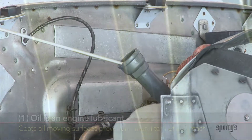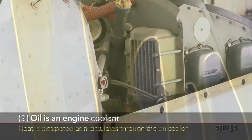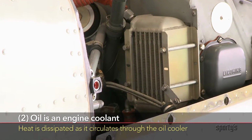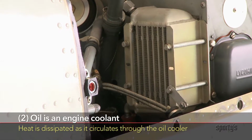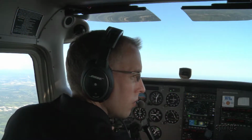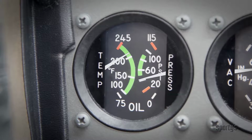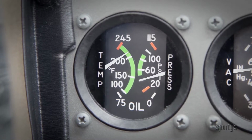First, it coats the surfaces of all moving parts with a slick film, preventing direct metal-to-metal contact. Second, it dissipates heat as it circulates through the oil cooler. And third, it carries any foreign materials to the oil filter. Because oil is required for both lubrication and heat dissipation, the oil pressure and temperature gauges are important indicators of engine operation and condition.